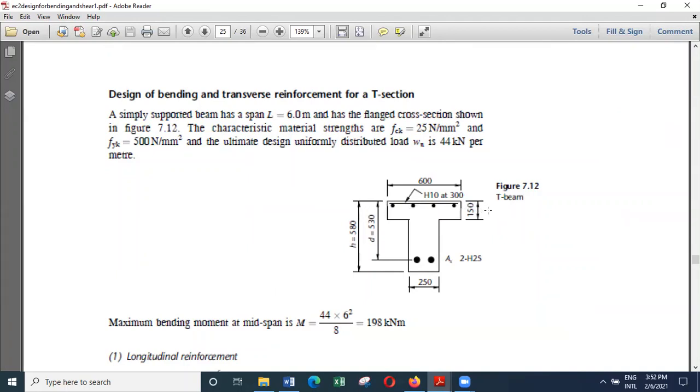And in most of the normal cases, the beams are not heavily loaded, so most of the time you will find the stresses are also low, and the provision of that reinforcement is sufficient, and generally we don't check it. But in the case of foundations, because they are heavily loaded, this situation can be more critical, especially in the case of inverted T-type foundations.